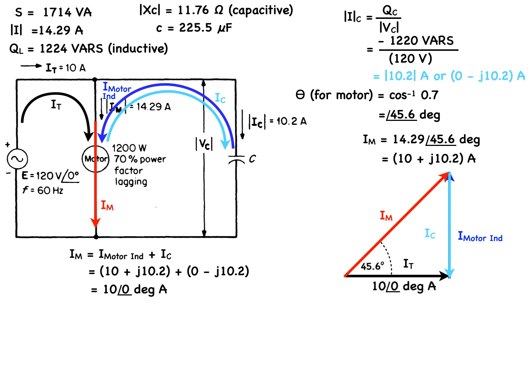Typically, power factor correction capacitors are rated in kVARs or kilovars and may be installed in switched banks to provide a range of power factor correction. The reactive current flowing in the circuit is between the inductance of the motor and the capacitor. These currents are 180 degrees out of phase and oscillate such that the current flowing from the source is at unity, as can be seen. The current magnitude in any of the branches at no time exceeds 10.2 amps.